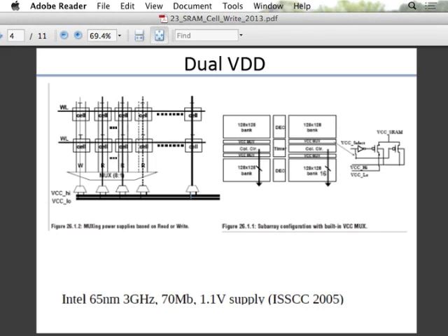So you have shown a lot of muxes, one per column, yes. That means each column's voltage can be controlled, but it's the same value. You don't give different voltages to different columns, because again you come back to this problem of generating those voltages.